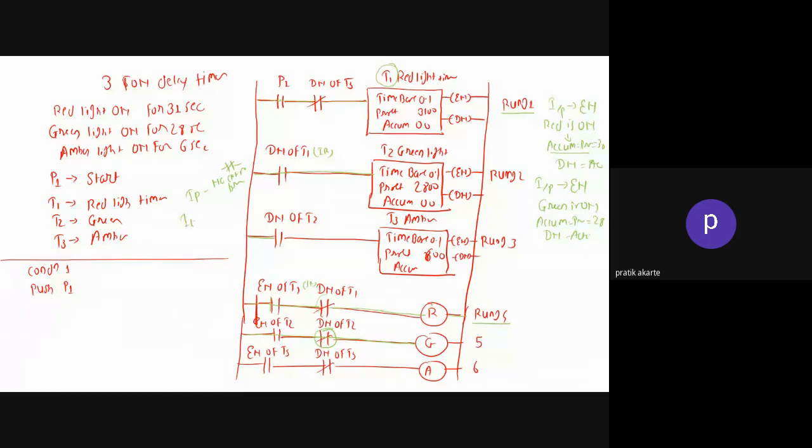When you get input and it is a normally open type of contact, your circuit is completed. Also, you should remember that these internal relays are memory locations associated with that particular bit, enable bit, done bit, or the switches that we are using. And as soon as they get the particular conditions, there is a simultaneous or sequential on and off as they get the inputs and outputs.